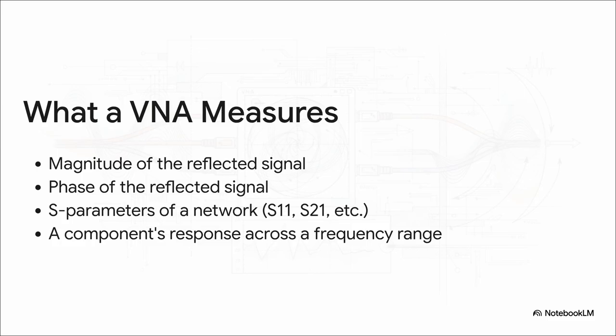So what is this thing actually measuring? Well, first off, as we said, the magnitude of the reflected signal, how much of it is coming back. Then the phase of that signal, what's its timing? This information gets packaged up into something called S parameters, and we'll talk more about those in a sec. And the coolest part? It doesn't just do this for one frequency. It sweeps across a whole range, giving you a complete picture of how your component behaves.